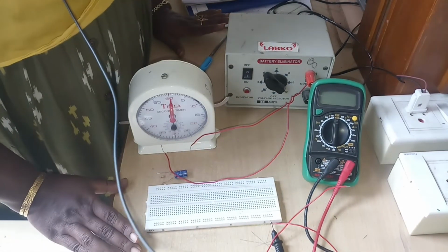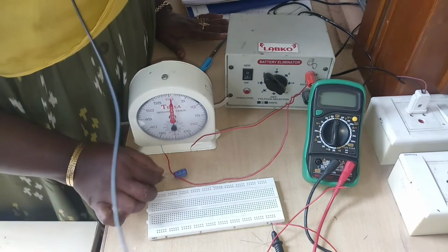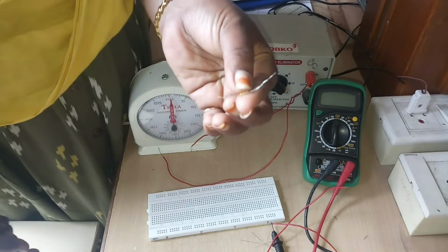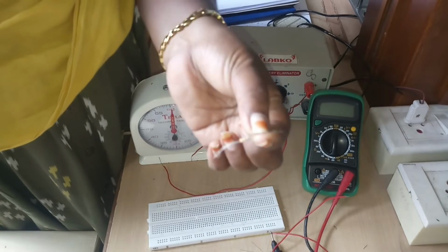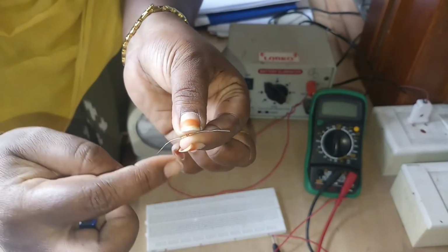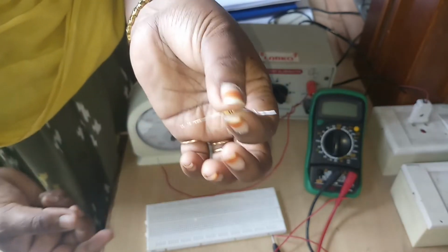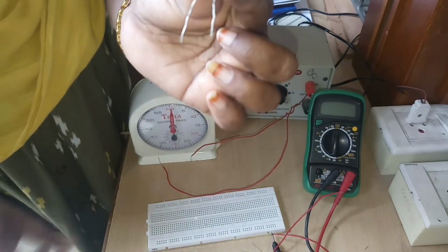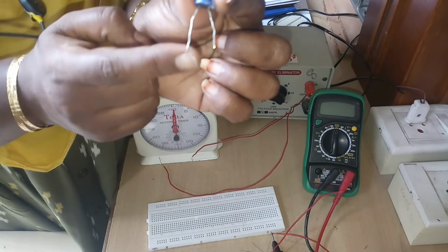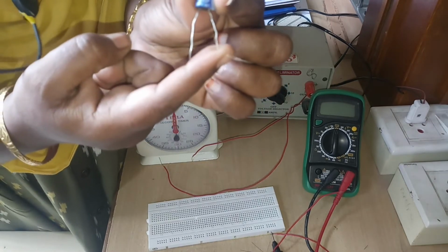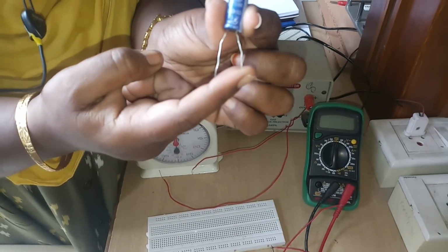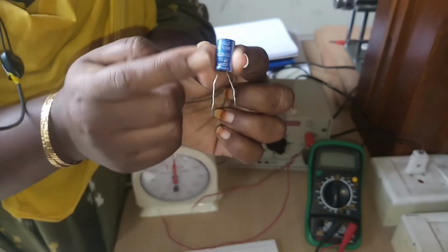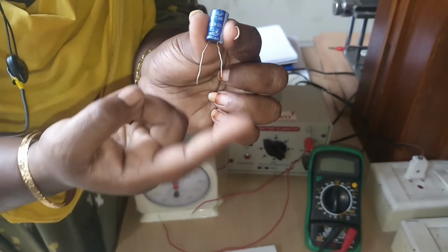Okay, let us see the apparatus required for this experiment. Actually, an RC, that is a resistor and a capacitor, is required. So this is the resistor. For this experiment we have taken a 100 kilo ohm resistor. For a resistor there is no polarity, that is positive or negative. In any direction we can give the connection. And then this is the capacitor. It is a 100 microfarad capacitor. By seeing this you can identify one leg is long and another one is short. The long one is positive and the shorter one is negative. For the capacitor you have to remember this point: this is positive, this is negative.